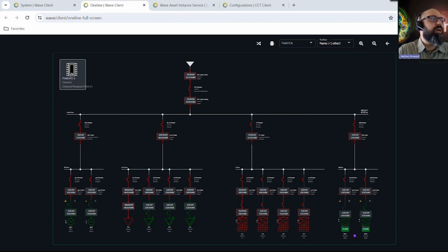And we'll see that as more and more renewable energy becomes available, we'll start closing the breakers to those controllable loads, just in the middle left of our one line. We'll be either charging those electric vehicles or creating some hot water or whatever the case may be, where we're able to take advantage of that instead of curtailing our production.